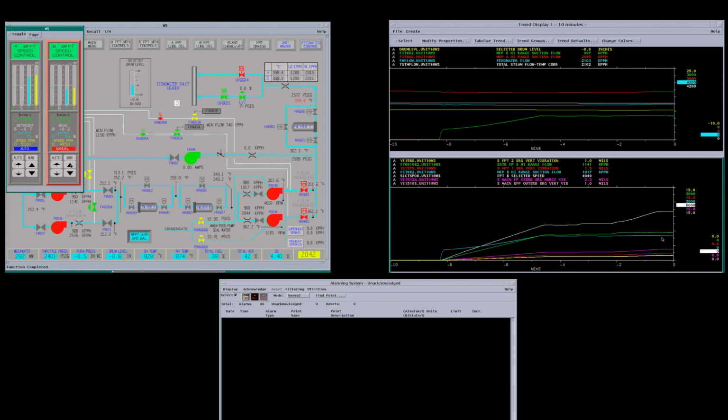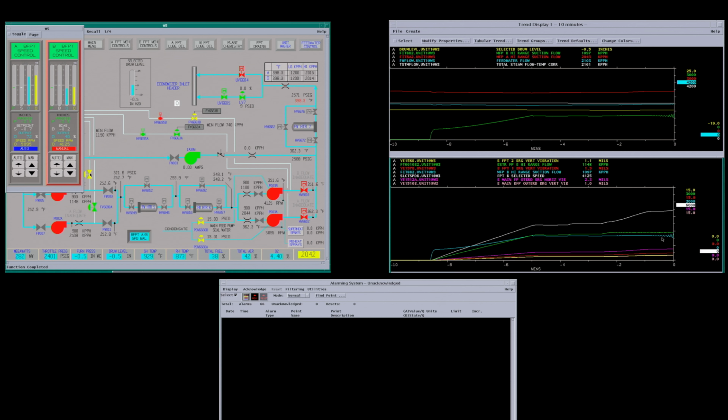Say this is something you really don't want to do to a pump, but you can see it's starting to move a little bit. It's starting to bounce around. Sometimes emergency shutdowns, when these recirc valves don't work correctly, it can move piping quite a lot. Okay, you can see we're starting to cavitate it. So you always want to make sure your recircs are in auto and they're working when you're starting up a large pump.